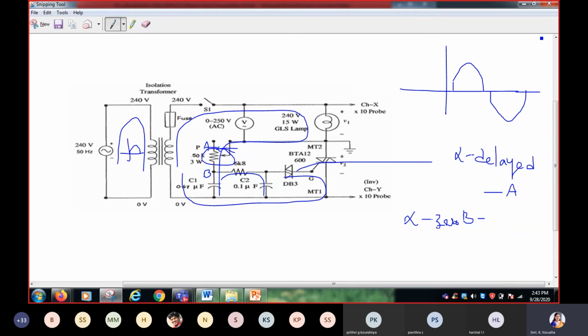So this is one more viva question. What is the advantage of digital control circuit over analog control circuit? In analog control circuit, due to devices like diac, resistance and capacitance, the firing angle what we achieve won't be accurate, and the range of operation will be limited. Here we won't get the complete range. 0 to 180 degree we won't get. The alpha range will not be with complete 0 to 180 degree.